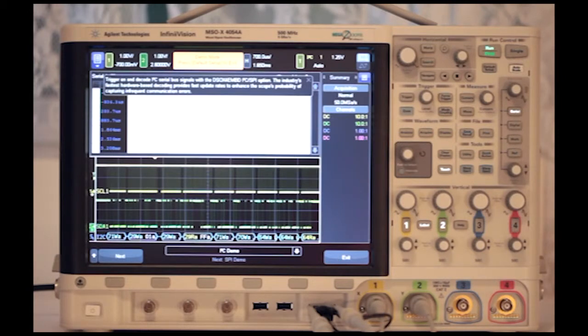It doesn't require much investment in hardware, making it ideal for in-the-box and on-the-board applications. It is often used in RF tuners, video encoders, decoders, and audio processors. Philips intended their innovation for inside TV sets, for communication between microchips, and for very short spans between boards.